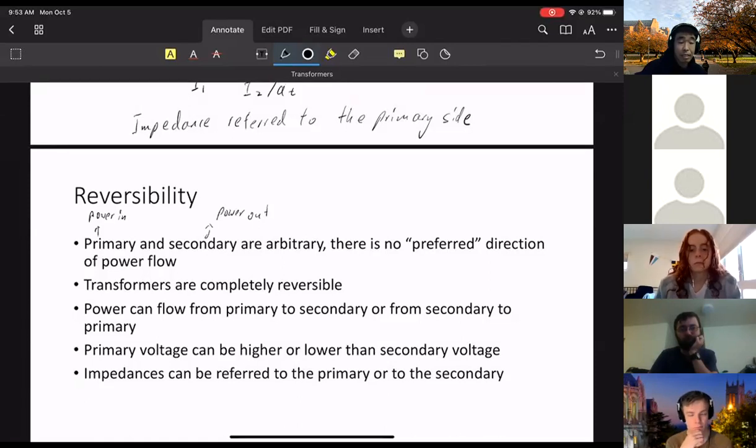Okay? So when you hear somebody say, "Oh, we have a lot of electric vehicles or a lot of renewables, we'll burn the transformer out because of reverse current flow," you may hear that on some news reports. That's not correct. The transformer doesn't care; something else is going on. So be mindful when you hear that it's not the transformer. It's some other equipment, which we'll cover later in the class. But as a piece of technology, it's irrelevant which way the transformer goes. Any questions about ideal transformers?